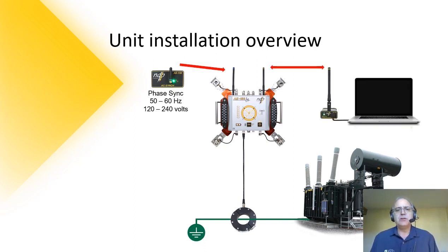And then you need to be connected. I mean, your computer needs to be connected to the unit, either to transmit commands or receive the data. So we have either a cable that runs between your PC and the AE-150, or we have a wireless optional transmitter module. If you're using the wireless, you are totally isolated from the unit, from the transformer, for safety, but it's one or the other that will transmit commands and receive the data.